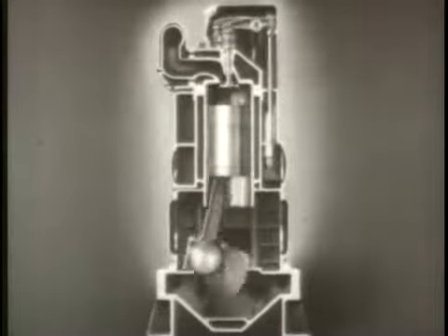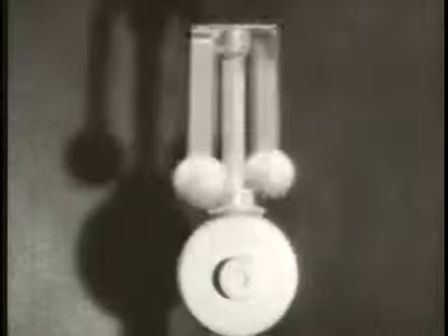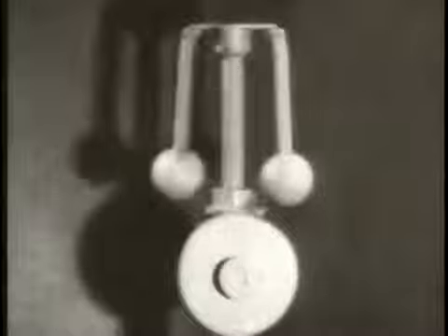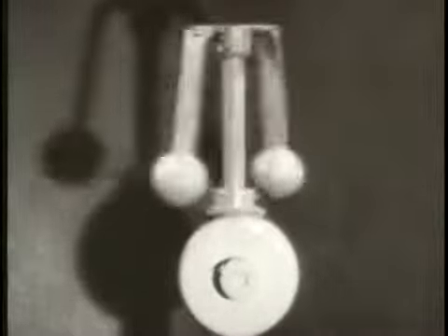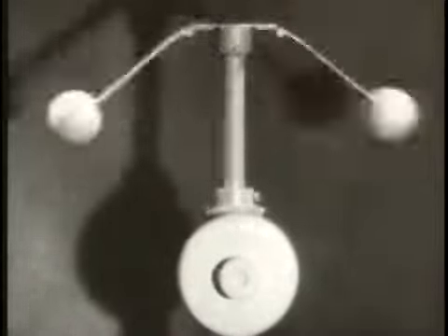To do this, various types of governors have been developed. Most governors operate on the principle of centrifugal force. Centrifugal force is the tendency of an object, when traveling in a circular path, to move away from its axis of rotation. These rotating weights are affected by this force. As the speed is increased, centrifugal force grows stronger, pushing the weights further away from their rotational axis. The distance from this axis is proportional to the speed of rotation.